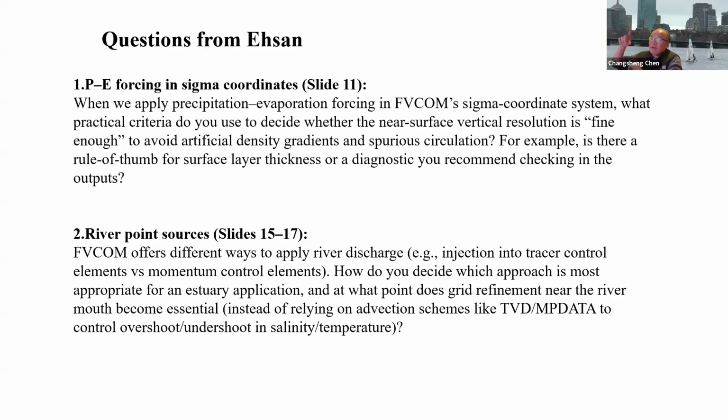because the sea level continuity equation is delta zeta over delta t equals P minus E divided by the density. That's why fresh water coming in directly affects sea surface level.